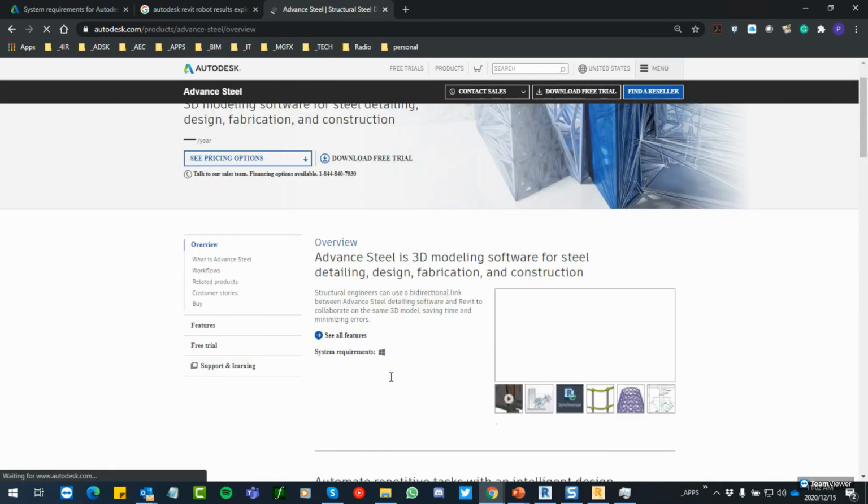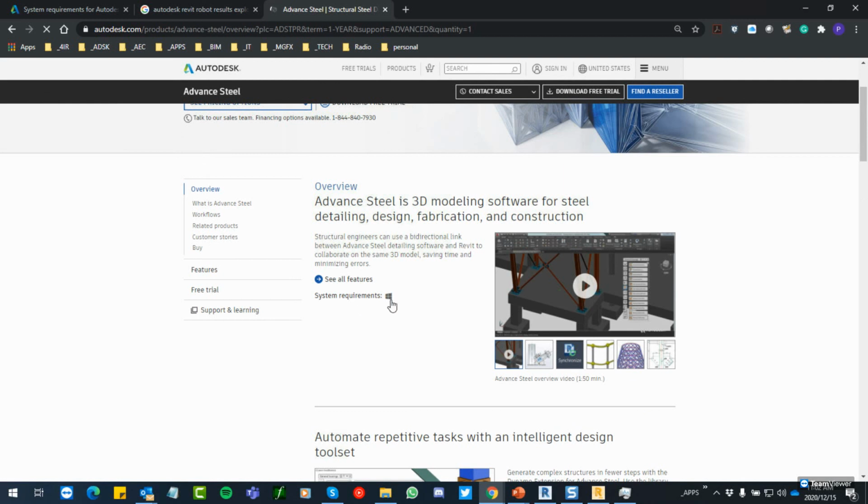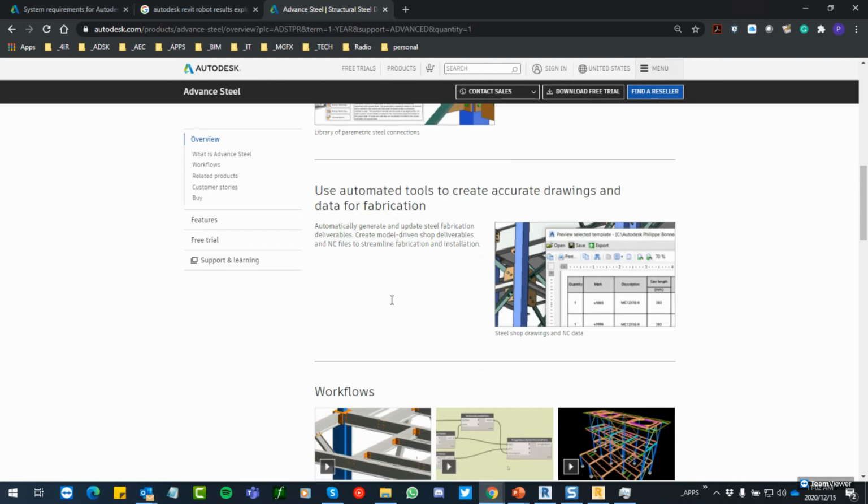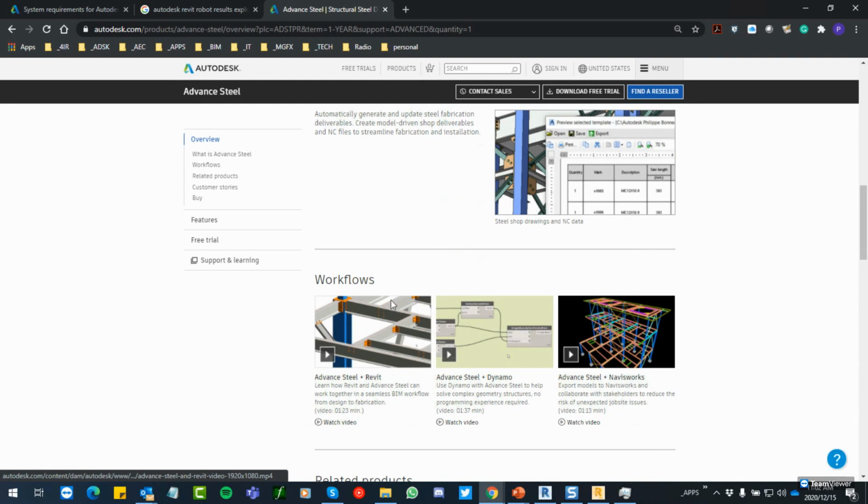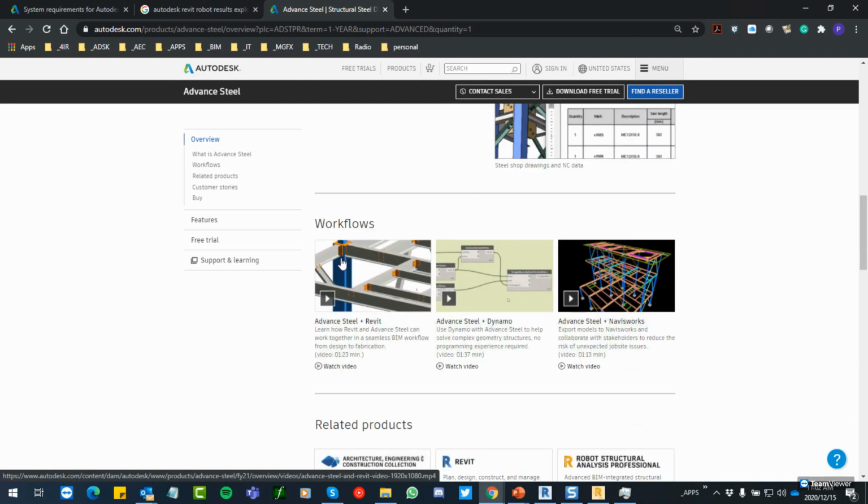I've actually worked through a course like this with Advanced Steel, and if you know AutoCAD, then you won't struggle with it. But this goes too fast too, and you can see Dynamo. But all the joins that you can do within Revit, it will port backwards and forwards. So if you have your joins in your Revit model, it will also show up in Advanced Steel. But in addition to that, you can set up custom joins within Advanced Steel that will be recorded as information, but won't show up graphically within Revit. It will just have a symbol to it. But within Advanced Steel, it will actually show that up to you. It will have the number of bolts, the washers, the spacing, the webbings, the welding